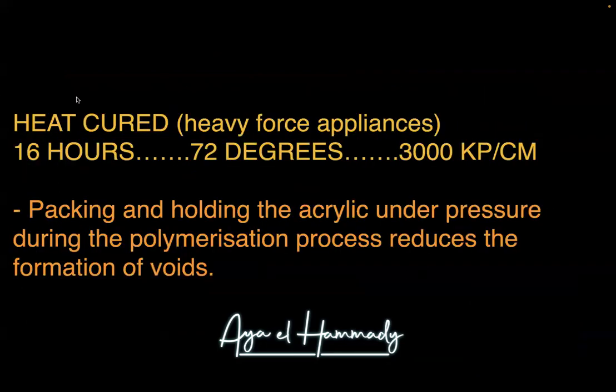Heat cured needs a lot. It's used in heavy forces appliances. I need to do it for 16 hours at 72 degrees for 3000 kilopascal. We need to pack it under pressure to reduce the voids. This is why when you are pressing, you are applying a lot of force with the spatula to relieve the voids, right?